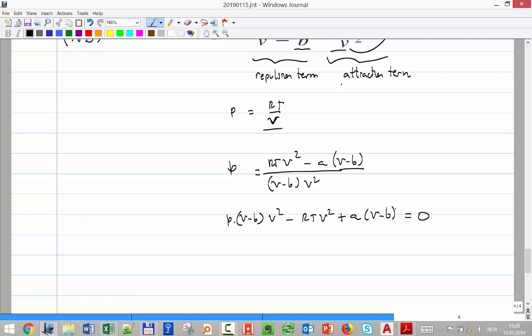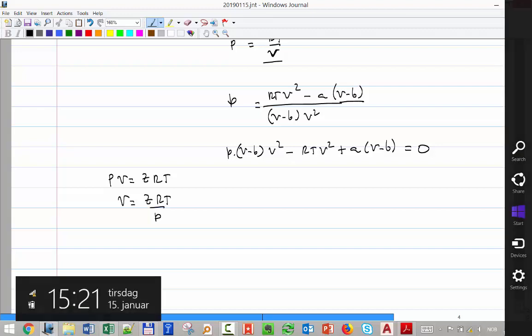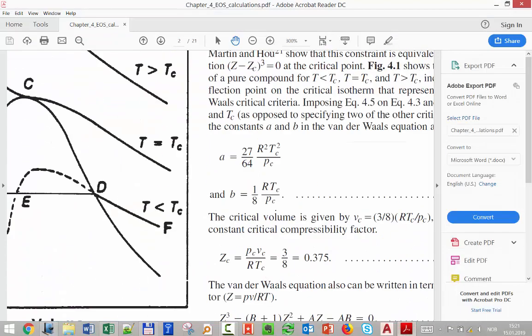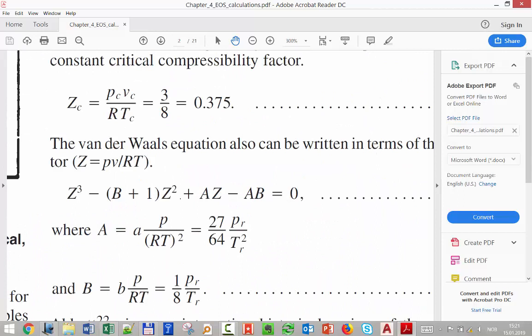in real life. But one way that people found that was slightly easier is to substitute the real gas equation. They say, well, we can still say that we have this relationship PV equals Z RT. But now we are going to substitute everywhere you have V, you substitute Z RT divided by P. And then I find this Z that doesn't come from the chart. I'm actually defining that parameter, Z, and that makes the equation slightly simpler. And that's the way I'm always solving this equation. That's the equation, and these are the coefficients a and b.